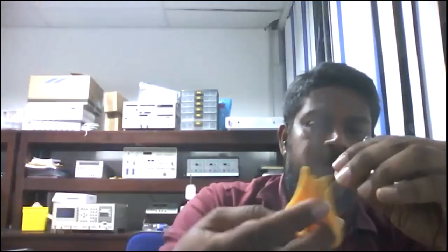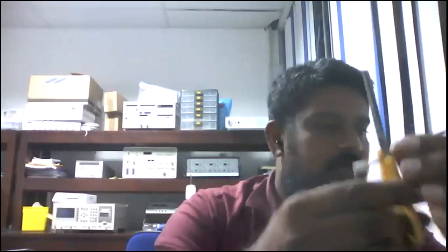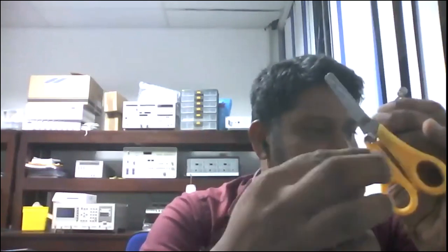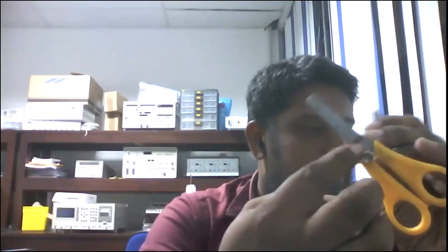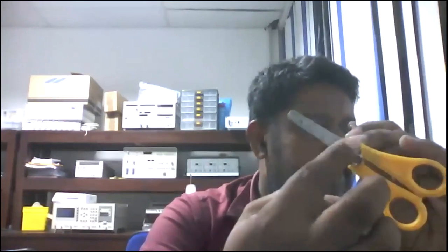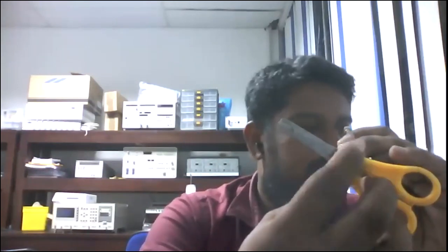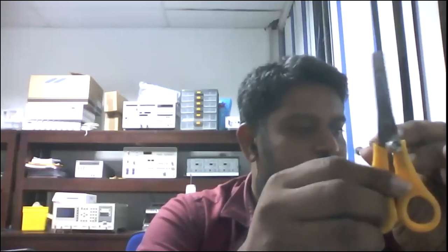So this bar is connected to this pin, and the ground. Consider that there is a ground plane, just like a copper plate like this. Then the ground plane is connected to this outer thread of the connector. So a monopole antenna is like this.